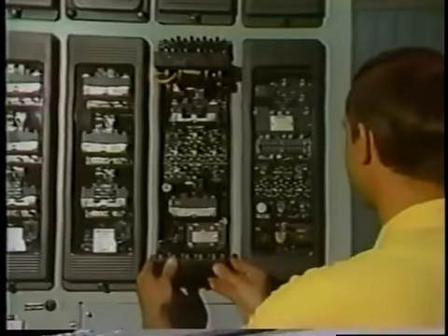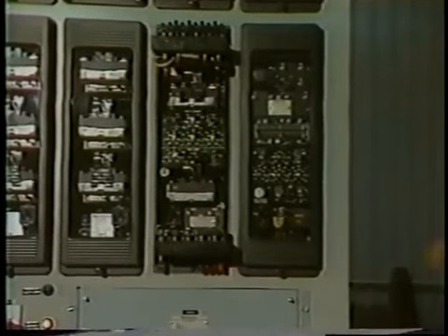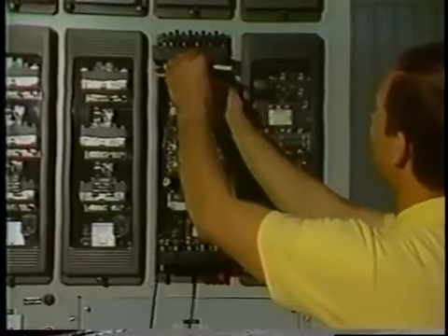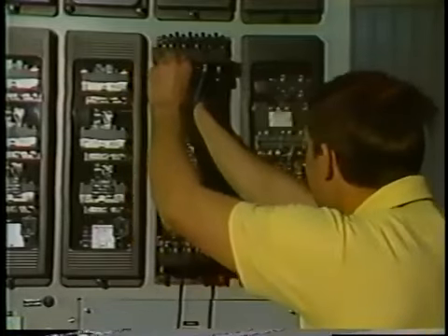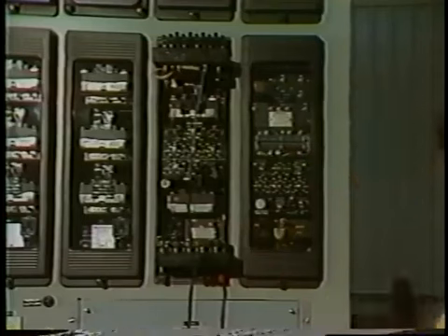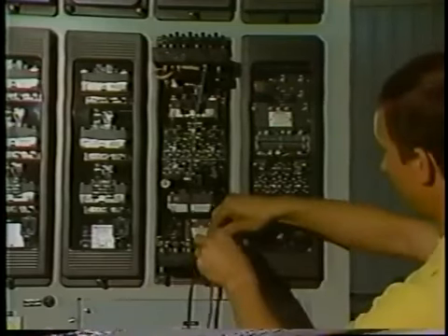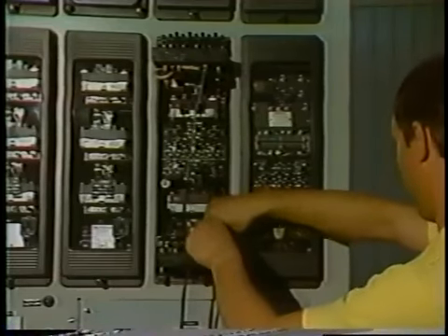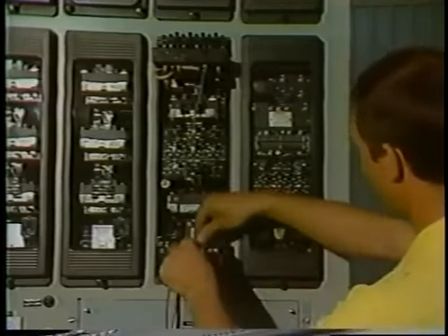We already know from earlier tapes that sensing information is provided to the protection system by coupling the relay to the load circuit through instrument transformers. Current transformers, CTs, and voltage transformers, VTs, step down the power system current and voltage to safe working levels. This provides significant protection to the relay and also to personnel working on the protection equipment.